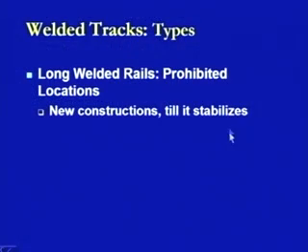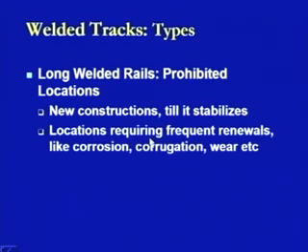Therefore, what is being suggested here is we have to wait till the section stabilizes, and as soon as the section stabilizes, then that section can be converted to the LWR section, that is the long welded rail section.